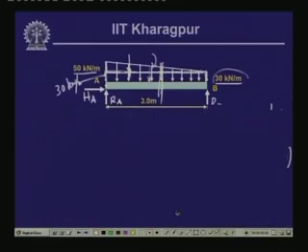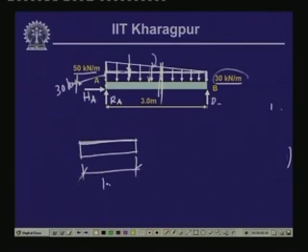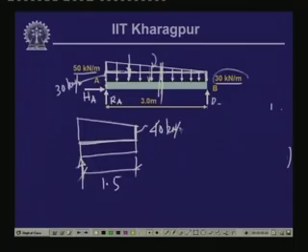Now, here we have this particular beam, which is of distance 1.5 meter, because this is the midpoint where we have the RA over here, and here we have the trapezoidal variation. Now, if you compute the value here, it comes as 40 kilonewton per meter, and this is 50 kilonewton per meter, and the positive shear is in this direction, positive bending is in this form. So, this is V and M.